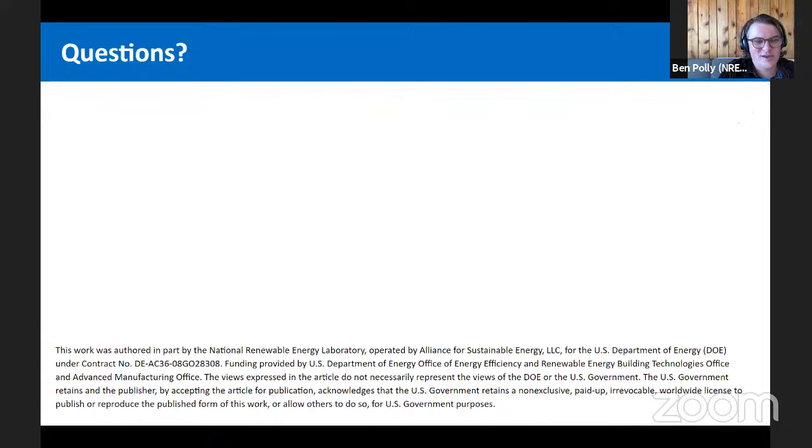Maybe some of the buildings are big enough that you have public disclosure requirements around energy consumption, so you might know annual energy consumption. But then the key question is how do you get a good baseline model for those communities? So we're definitely going to be looking into calibration and benchmarking against measured data.